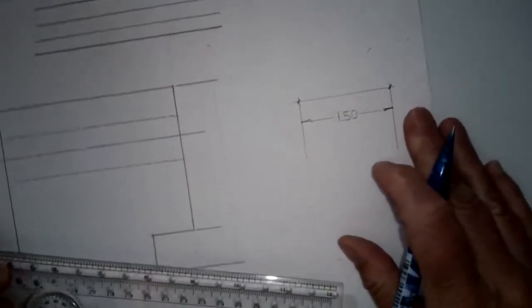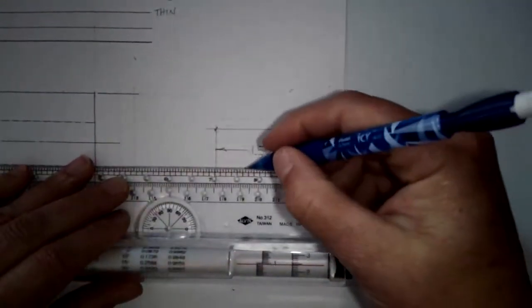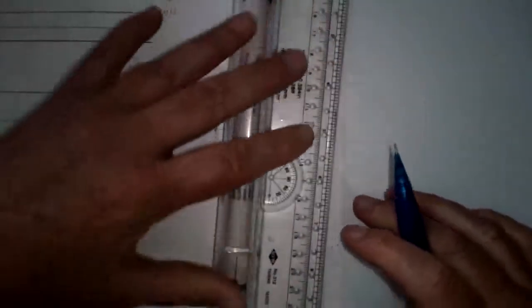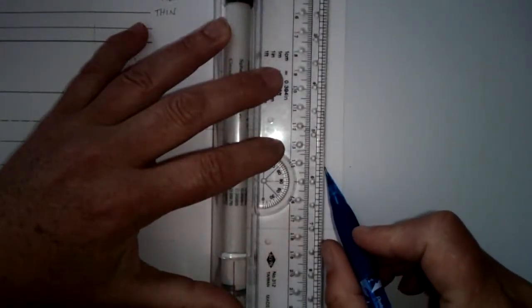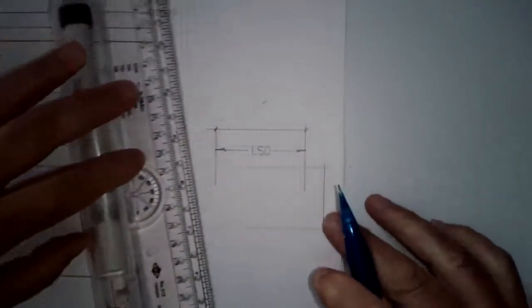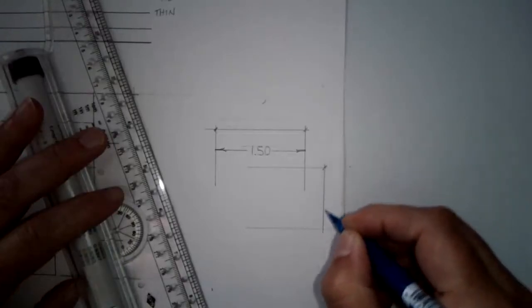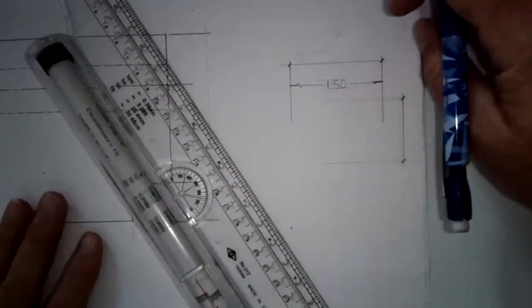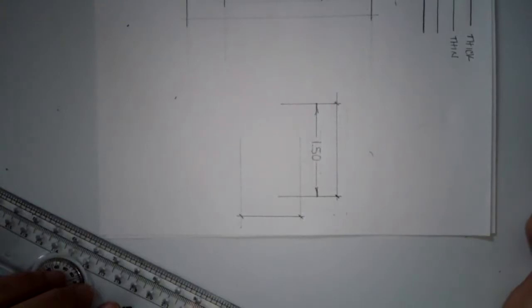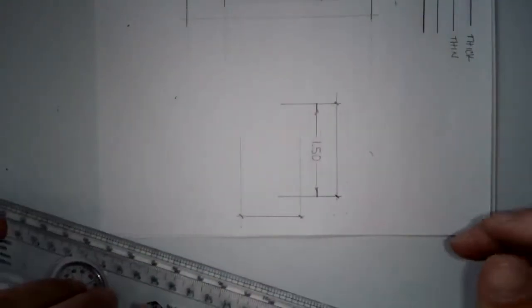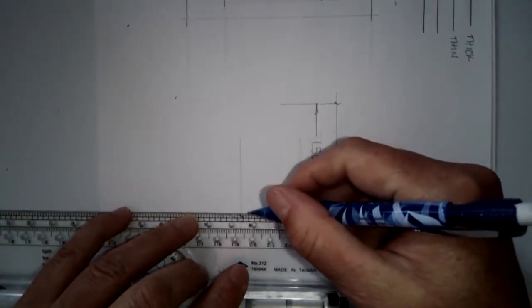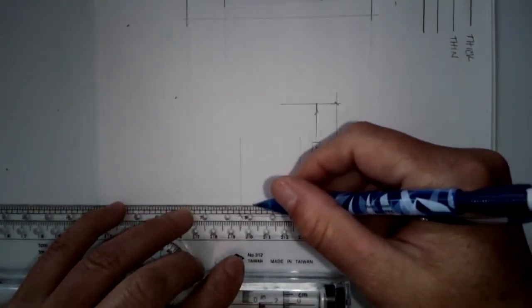And we always read, if we have architectural dimensions that are going this way, the two ways that you read architectural dimensions are from this position, like this on the page, and then you're always going to turn the page to the right, clockwise, and that's how you would position your dimensions in that direction.